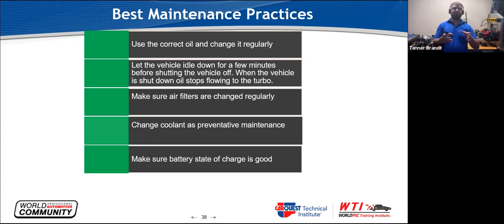As the state of charge of a battery goes down on a BMW, they start to load shed and get rid of things they feel aren't necessary. One of the first things they load shed is the after run of the coolant pump, which continues to pump coolant through the turbo to help it cool. So if battery state of charge is low on a BMW, it's not going to run the coolant pump, and in return it's not going to cool the turbo, and it's going to end up with premature failure.